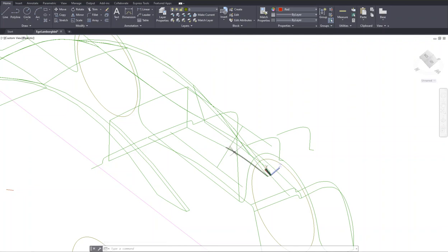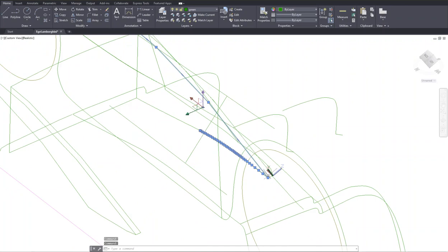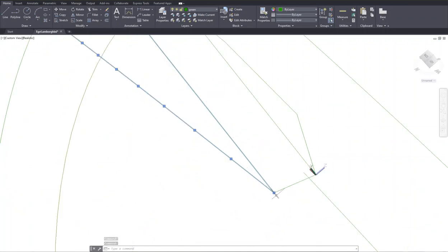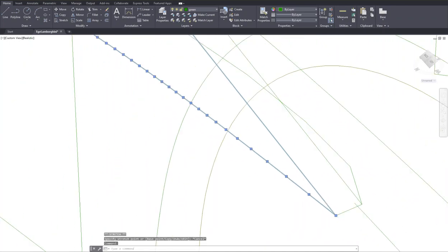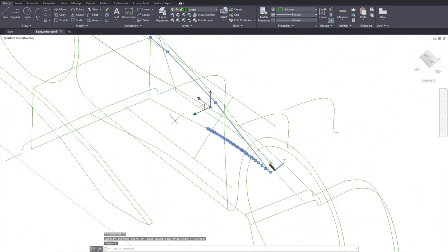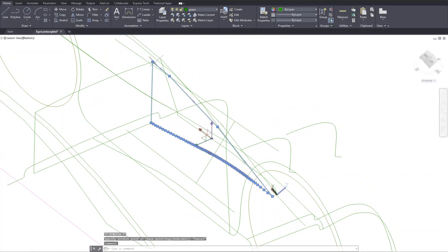Okay, so I did not like one of the line ends not meeting. It is a very common problem, and so you need to test it out to make sure that all the line ends meet. If this happens, do what I do: click on it, and see if, when one line is moving, the other lines are moving together. It's extremely important that line ends meet.